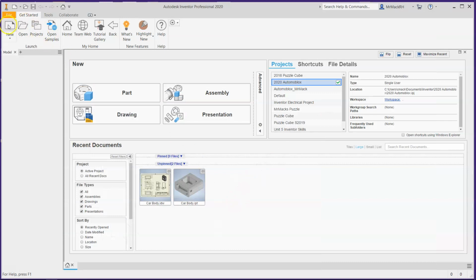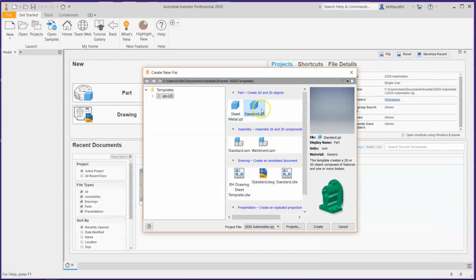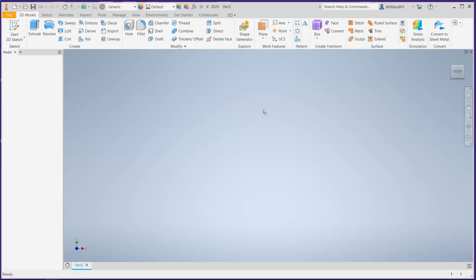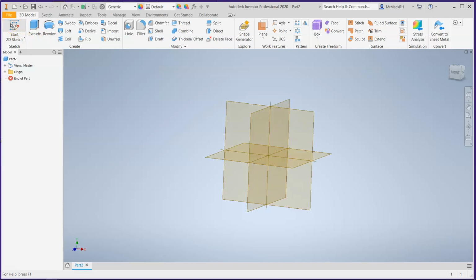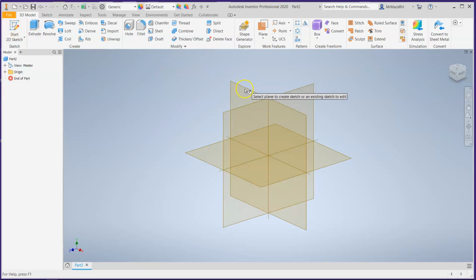So we're going to start a new part. So click on New, Standard.ipt. And here we are. Yours may take a little bit longer to upload. That's fine. Start a new sketch. And once again, I usually use XY plane, but you can use the YZ. That's fine.